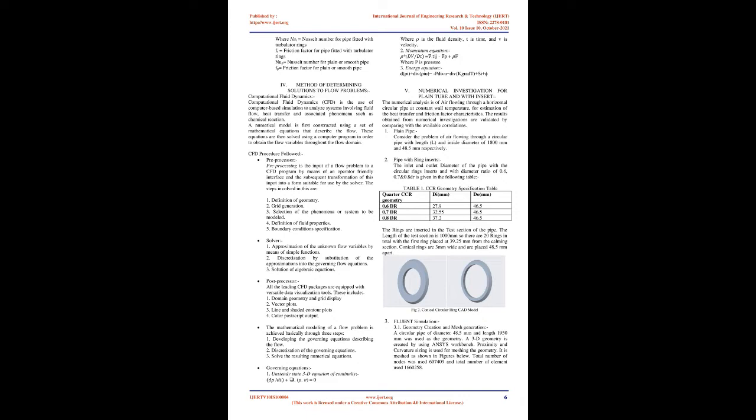To avoid such a condition at the outlet, to get correct readings, baffles are inserted at the outlet of the pipe to maintain the uniform temperature of air by thoroughly mixing it after the outlet so as to get the correct output temperature reading. The pressure drop across the tube is calculated with the help of the U-tube manometer.